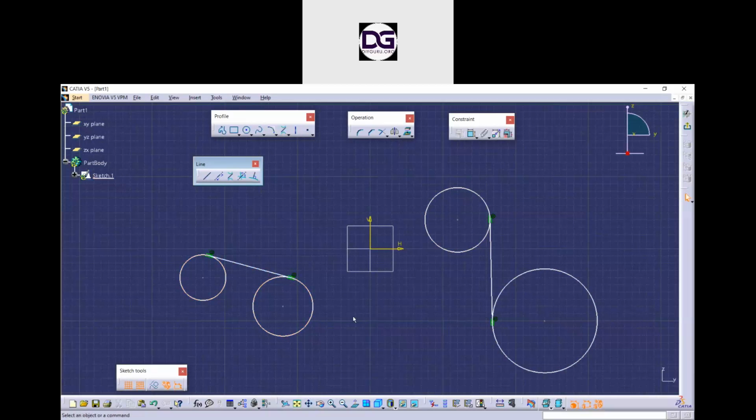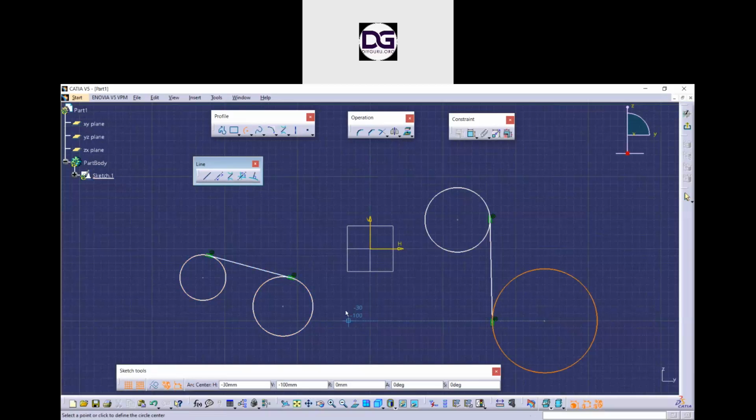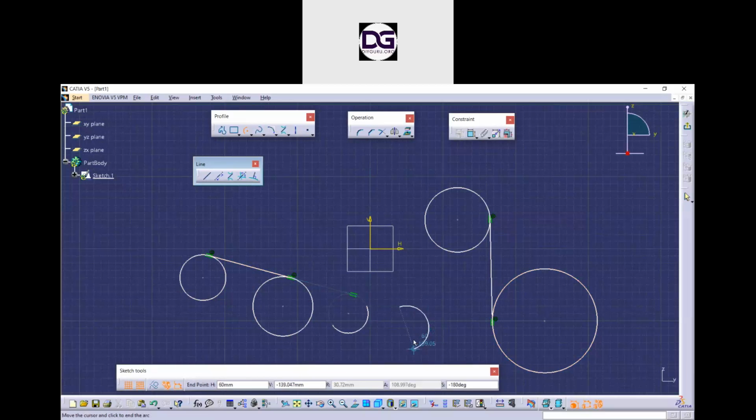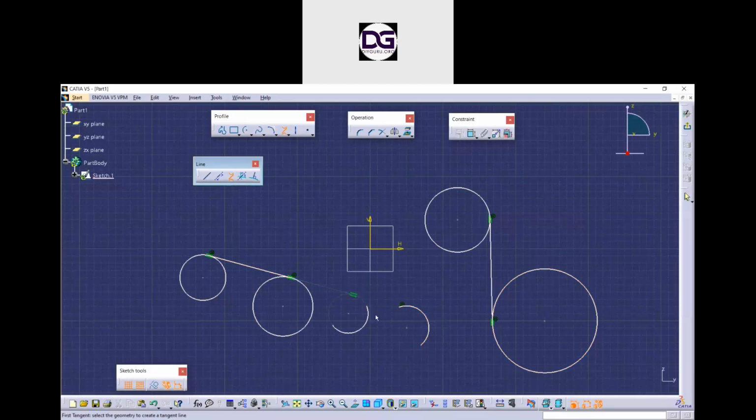It does not necessarily need to be circles only. You can have two curves, select those two curves, and the line will be tangent to them. Let's see, if we have two curves, this one and this is the second curve which I have. Now select the bitangent line and I will select these two curves. You see a tangent line is drawn here also. You can select any two curves and the line will be tangent to both of those curves. That's the bitangent line.